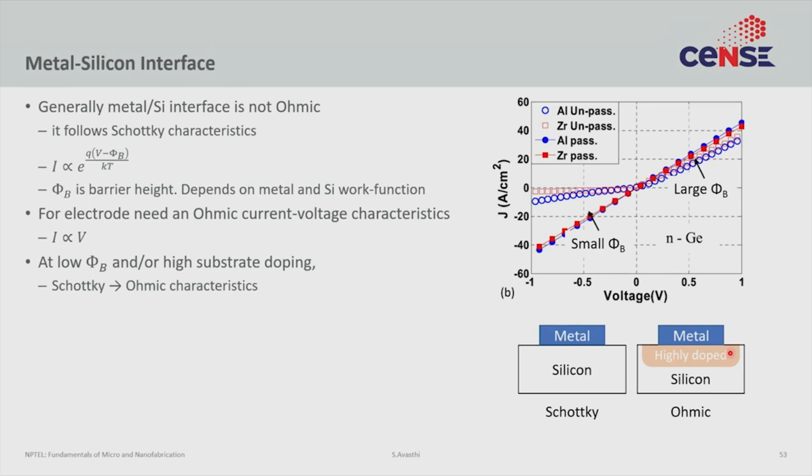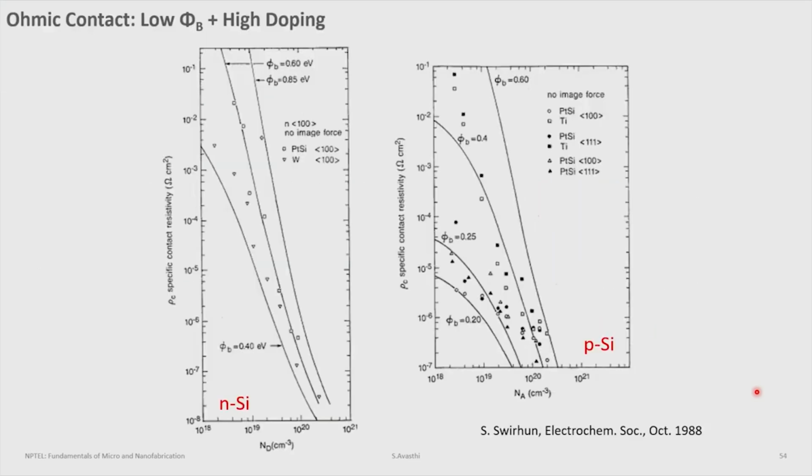And what this allows you to do is tune the band gap, the work function of silicon. So, that is one. The second thing, it ensures that any barrier between metal and semiconductor is so narrow that carriers can effectively tunnel through it. And that allows you to effectively have a small barrier, all right. So, this is a common trick to actually get ohmic contacts even when the work functions between the silicon and the metal do not agree. So, these and a few other tricks are what people use to make good contacts.